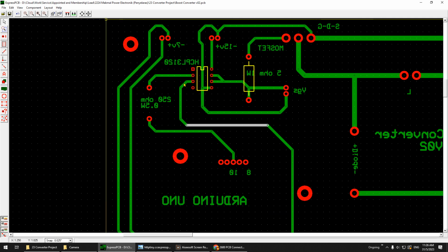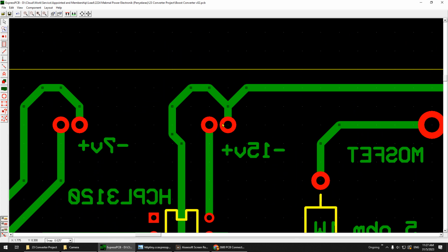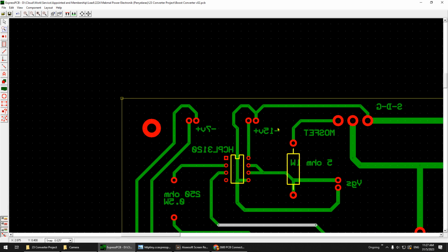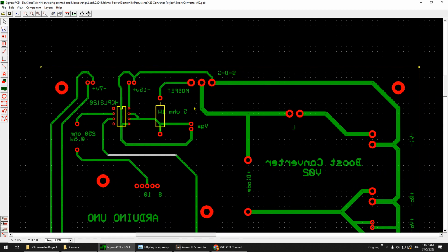But if you do this, the corner is not too severe and harder to damage during the etching process. So I suggest you put 45 degrees, easier for you to do etching, something like this. You can see here, instead of just making a T, which can easily be damaged, I put something like this. This is just a limitation of heat transfer and the etching process. So I suggest you do this.